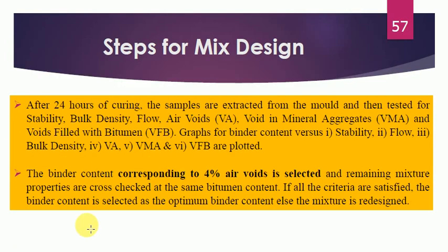After the compaction you should leave the specimen within the mold for at least 24 hours for cooling down of the specimen, or you can say curing. After that the samples are extracted from the mold and then tested for the stability, the bulk density, air void analysis, the VMA, VFB, which are calculated by using formulas.